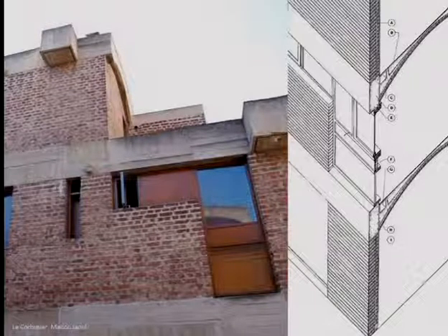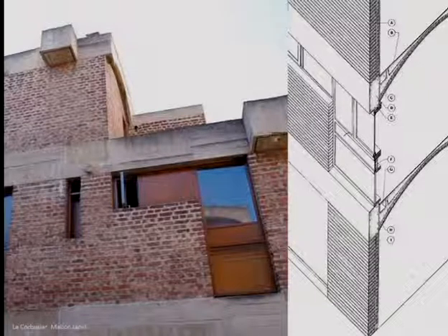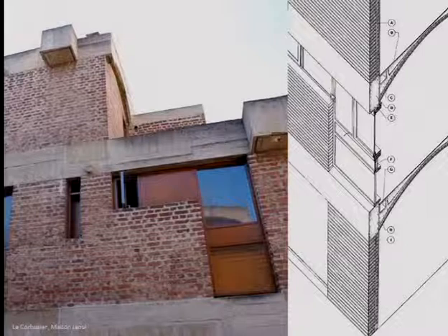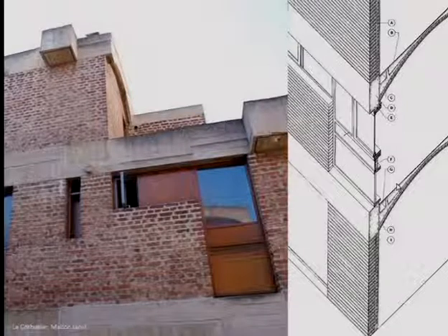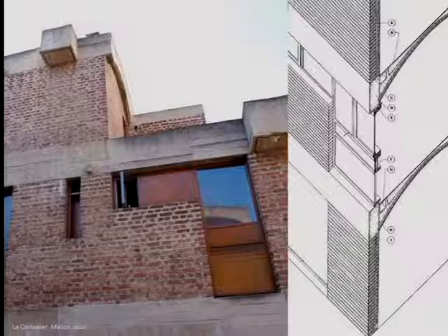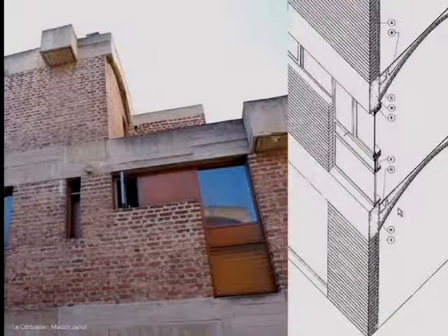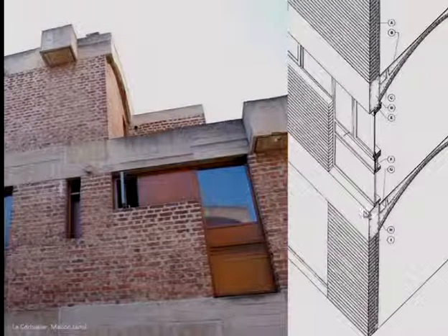The second thing is a little bit more technical. Nowadays, you won't do this probably, because you would get several thermal bridges. So to bring the structure on the facade, as you see in this image on the right, means that you have a direct connection between exterior and interior without insulation. There is no possibility to place insulation unless you literally make a coat, like you place it on the outer side.